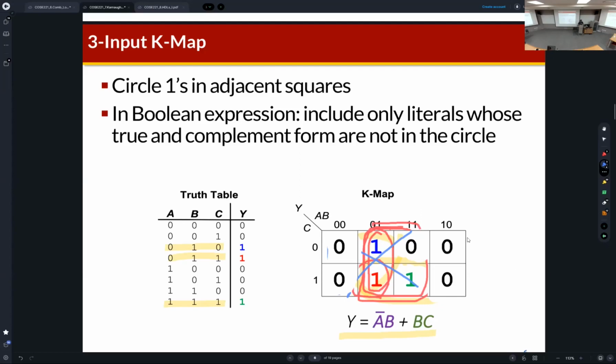This part is connected to this line. Okay? The Karnaugh Map is connected like a circle, a cylinder. So when this is 1, this is 1, 1, 1, 1, then we can group the ones like this. Okay, so it's very important.